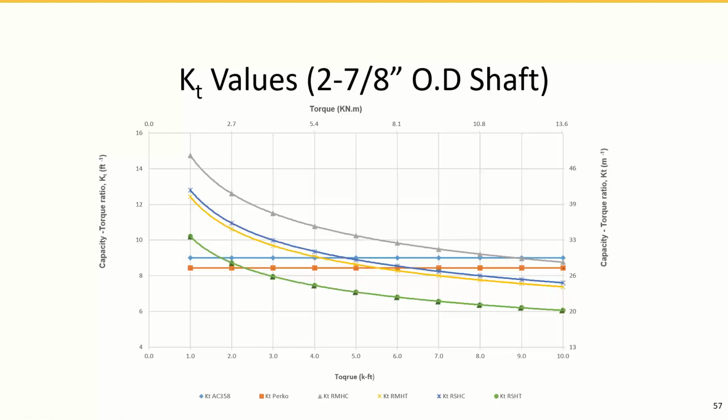Like I said, I find that in tension, generally, the capacity is about 10 to maybe 20% less than in compression. And do you know why? The reason is, imagine you have the same helical pile and you're going to test it both in tension and compression. First of all, when you test it in compression, that lower helix is sitting on non-disturbed soil.